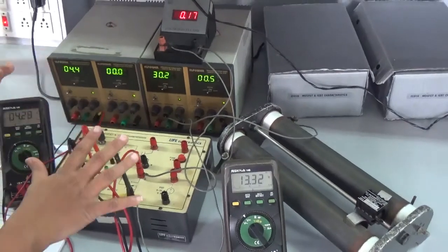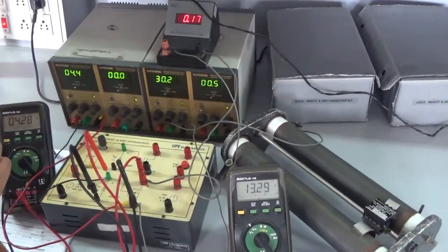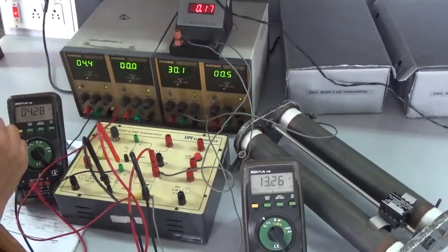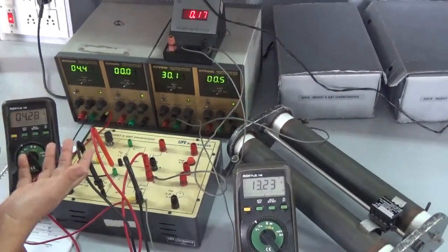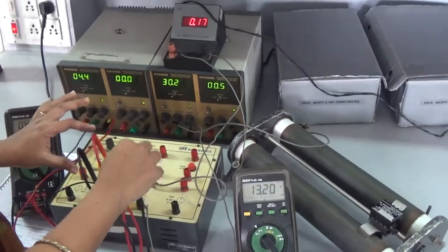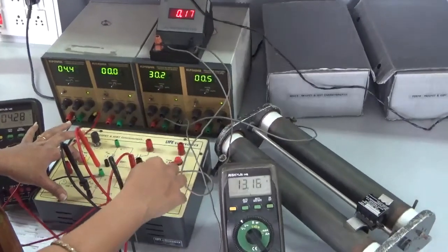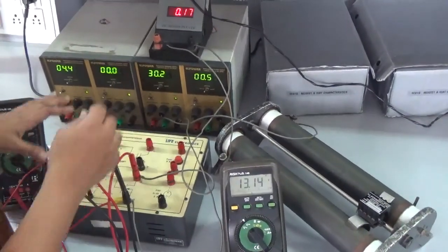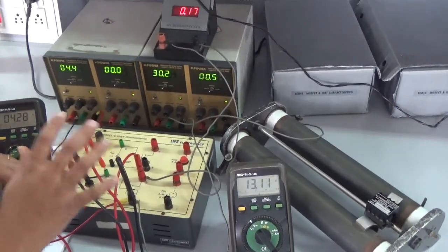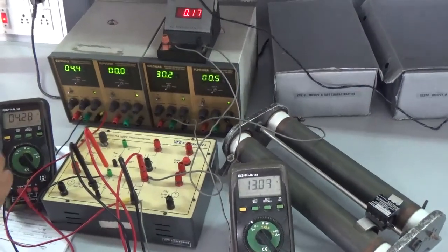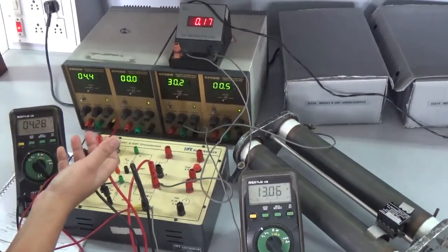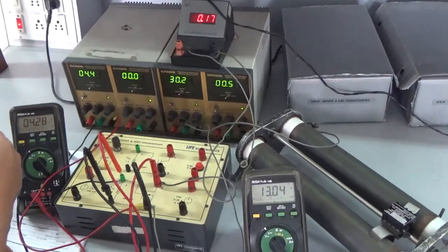and the entire procedure remains the same for IGBT. I am not going to show it again for IGBT. You have to repeat the same procedure for IGBT. The only difference is instead of using the GDS terminals, you will be using GCE, the terminals of the IGBT. The entire procedure remains the same. This is about the conduction of static characteristics of MOSFET and IGBT.